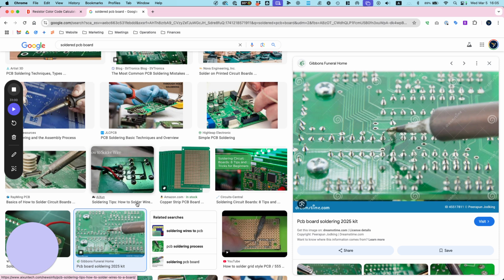Okay, I suck some of it out. And now, if you look, I suck a little too much, which is fine. I'm just going to put more because, you see, I'm missing some portion around it. So I'm just going to put a little bit more solder on. Don't apply too much, right? You can see that other case was already considered too much. Okay, so I'm just going to put a little bit here.